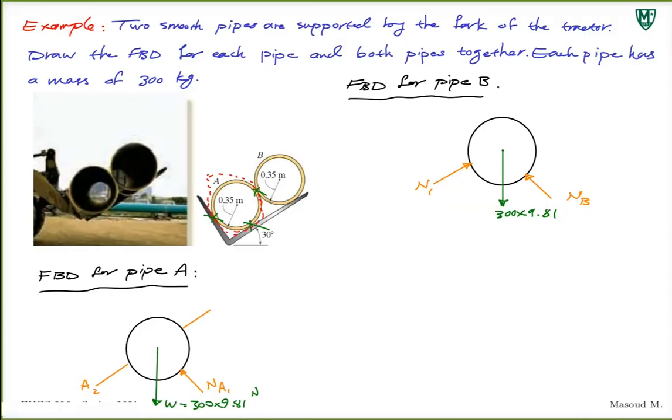Remember, on a free body diagram, a force should either be mentioned by a parameter or a variable, or should have the magnitude on it. If you know it, put the magnitude or value. If you don't know it, use a parameter to name it. But a free body diagram always has to have all the forces either labeled or with values.